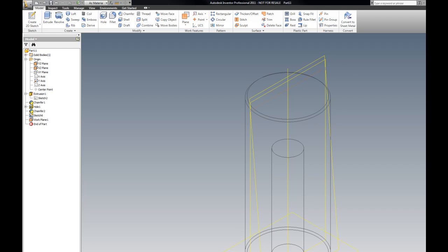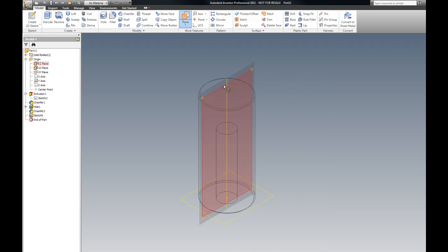And I'm picking this plane, and I'm going to go pick my line that I drew, okay, and I'm going to hit enter. Come on now, there it is, and I'm going to type in 5 degrees, and you can see that it's tilting just off the top, and that's not what I want. I want it to tilt a different way, so I'm going to type in 85. There we go. So it's going to go up 5 degrees. Okay, I'm going to go OK.